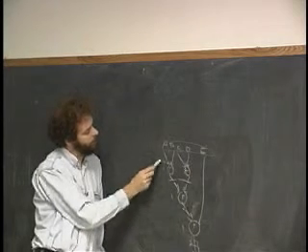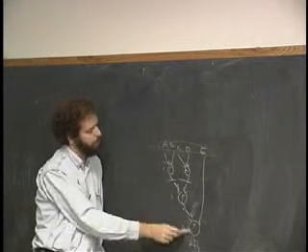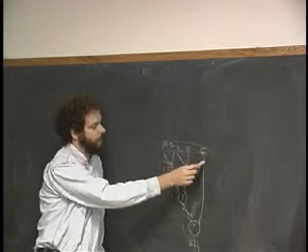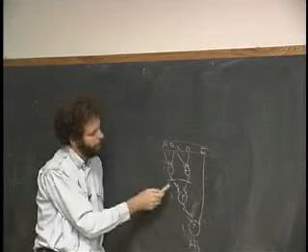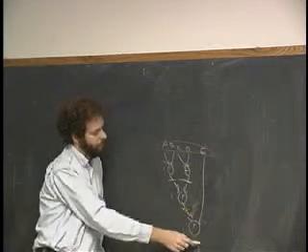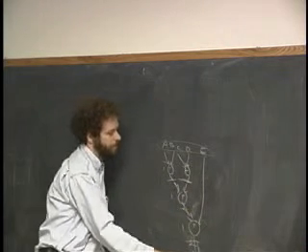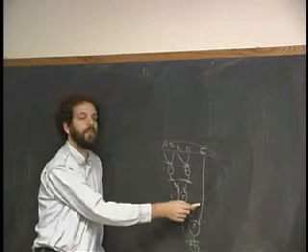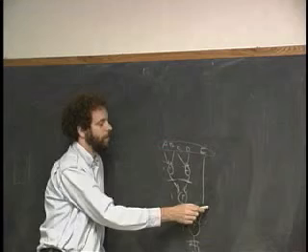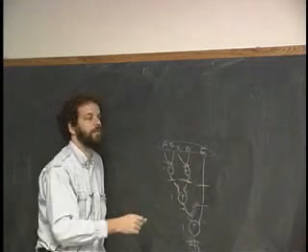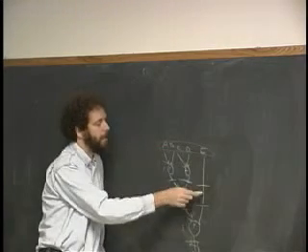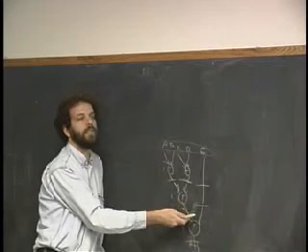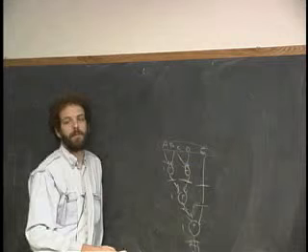Well, let's see if that's true here. Here we have 1, 2. 1, 2, 1, 2, 1, 2, and then we have, I'm sorry, 3. 1, 2, 3. Here's the output. And here we have just 1. So that's wrong. So what do we need to do here on this wire? We need to insert 2 extra registers to time delay E so that these other data values can catch up with E, and so it can be considered at the same time.